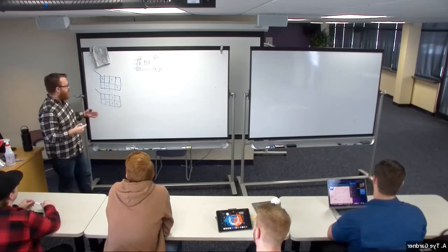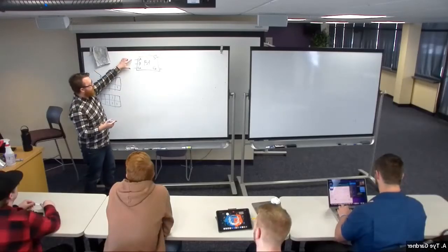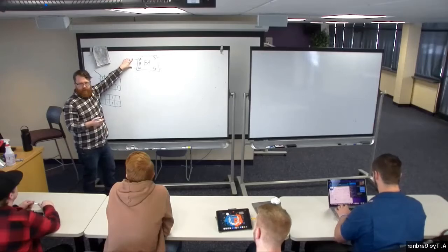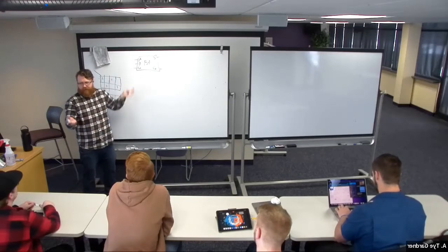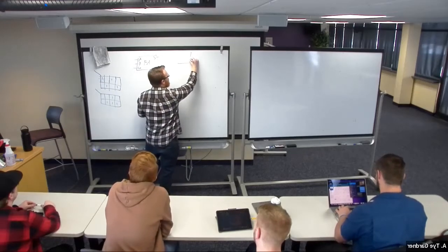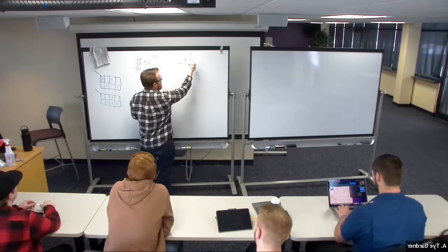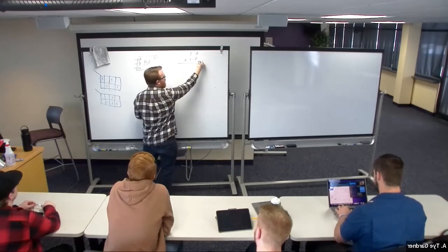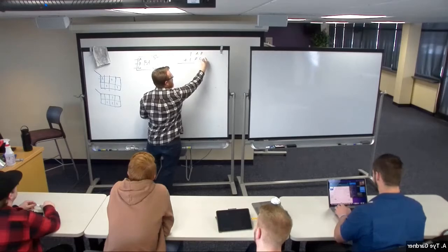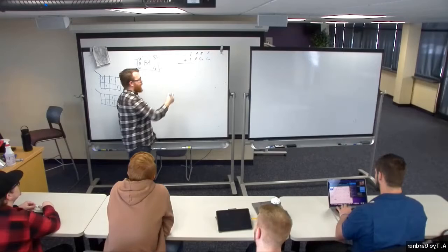And all it's saying, when you circle it, is that in an adder, if you have any 2 inputs that are ones, I get a carry, right? Because that's just the definition of an addition in binary. 1 + 1 is 0 with a carry. Doesn't matter if this is A and B, or B and C in, or A and C in, or all 3 of them. So you have this expression,